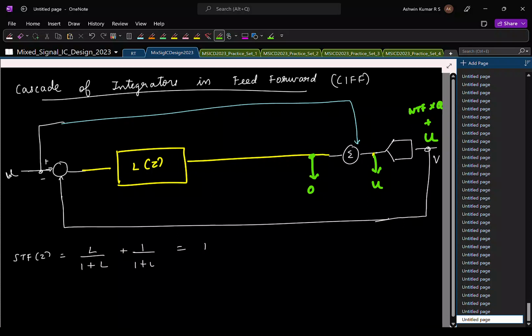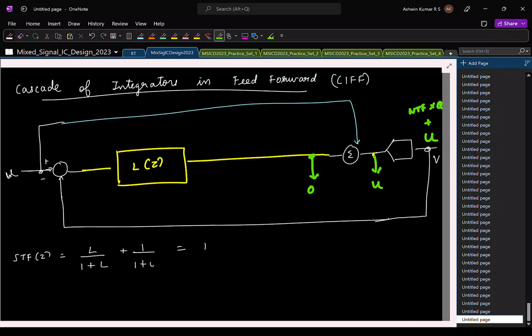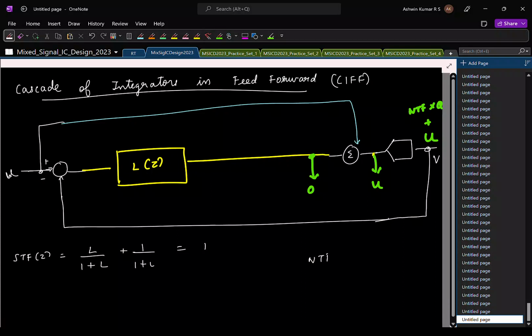For considering only the signal path, I have ignored quantization noise. Notice that adding this is not going to change anything in my NTF, because the entire thing starts from a particular NTF. You design a particular NTF, and from this you find a loop filter.